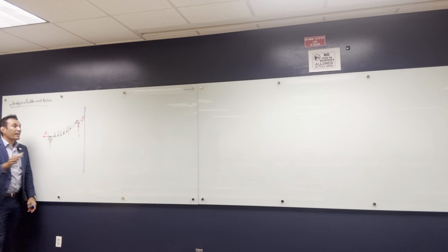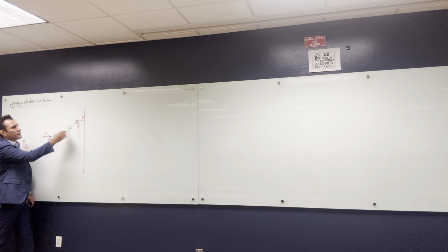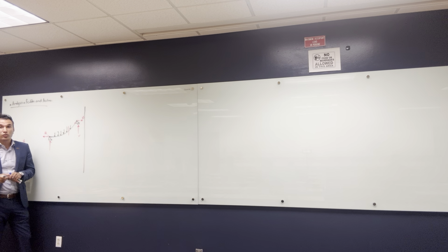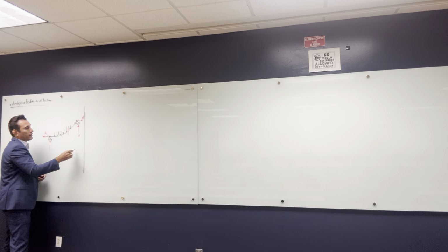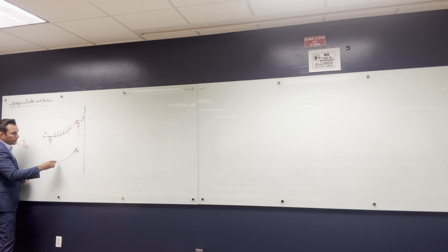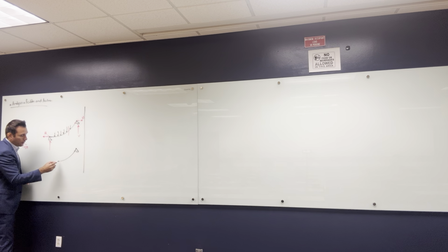So we have a horizontal force, and we came to a conclusion that, as long as the cable doesn't have any horizontal loads, do you guys remember what the tension in the cable is equal to? H over cosine theta. H over cosine theta. So how did we come to this conclusion? We said that we are going to take a section in this cable, and once you cut a structural member, all the internal forces show up. Like my cable is something like this. Once I cut this cable, the tension in this cable shows up something like this. It has 2 components: let's say this is T1, it's going to have a vertical component and a horizontal component H.